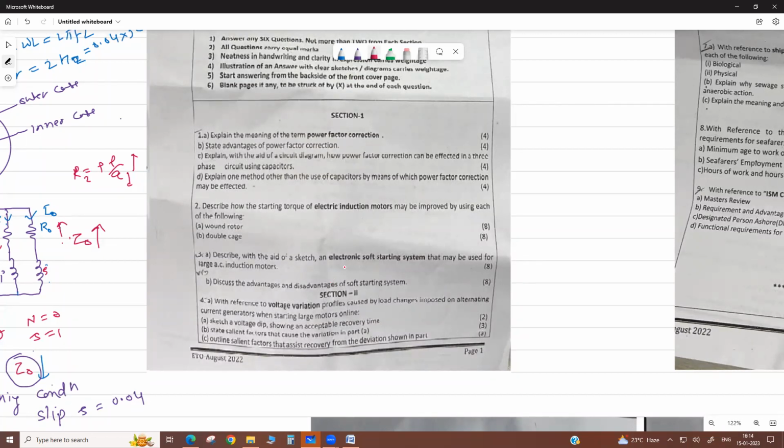Okay, but in soft starter, it will gradually increase the voltage. And this soft starter is also used for speed control. Star delta we cannot use. You know, this soft starter we can use for speed control. How? You reduce the voltage by controlling the firing angle. Then your motor speed is controlled. Okay. But with star delta, we cannot control the speed. Correct, na?